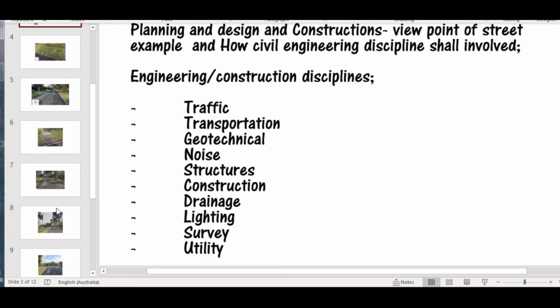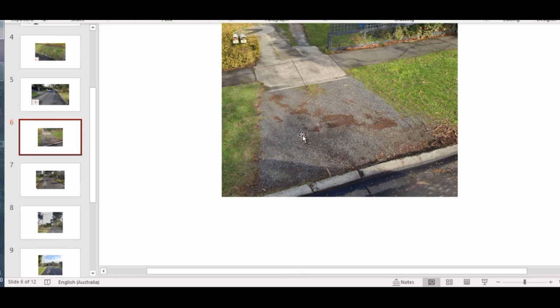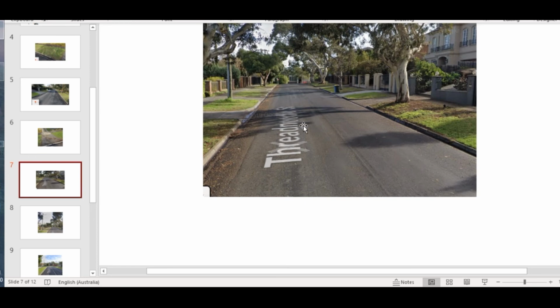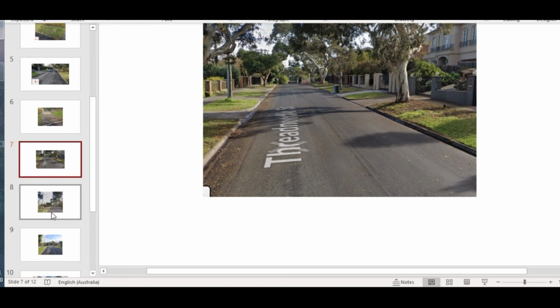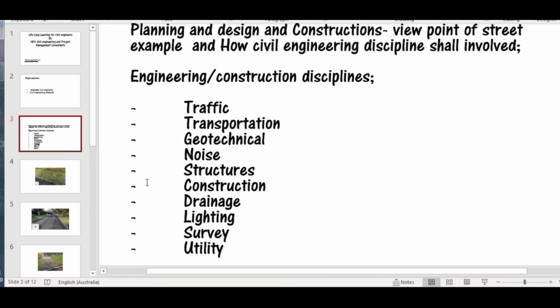Survey, as I mentioned earlier, is all about getting a real picture of the ground, what the ground is all about. There is a bit of crossflow of the existing road, capturing all information available on the ground, including maybe valve connections, driveways, kerb, gutter, lip, centerline, road edges, bitumen, trees, spread of the trees, canopy of the trees, so that we can efficiently plan from that point on and design and provide the right information for construction. So these are the surveying information we require at the initial stage. That might be done by sophisticated tools, techniques and software.